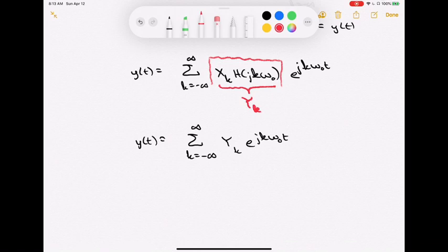For linear time invariant systems, the building blocks that are simple are going to be these harmonically related exponentials, in the case of an input being periodic. And because of the beautiful properties of a system and how it acts on everlasting exponentials, we get a simplified output that is very similar. It's a sum of sinusoids, each weighted by their own Fourier series coefficient as well. And we can get those coefficients through a simple multiplication.